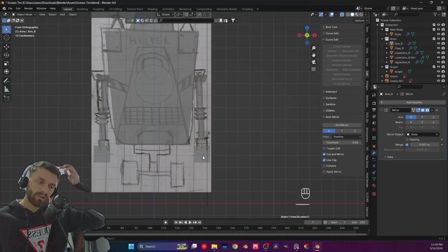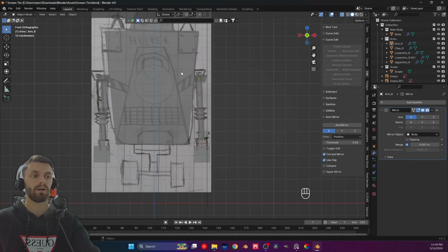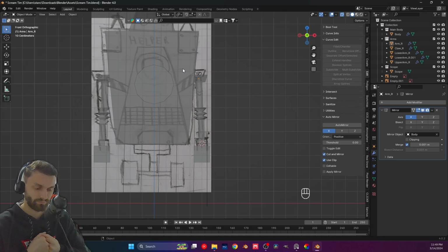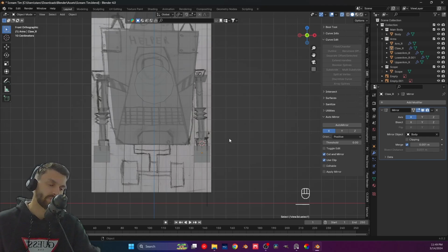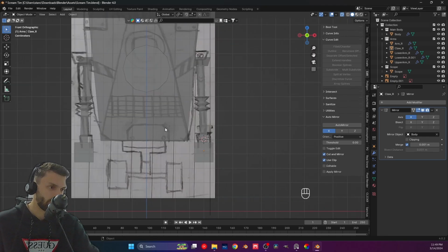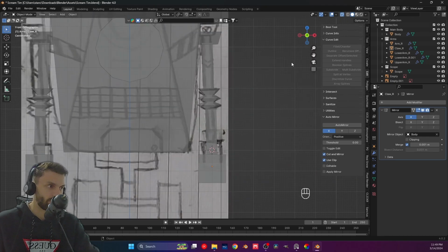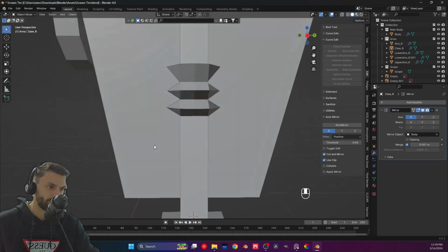And what that does is it will take the modifiers that this shoulder has, and it will apply them to the others as well. However, you have to understand that when you do this, you copy their modifiers. So if you have, for example, another modifier on the claw here, and you copy the modifiers from this one, the modifiers that you had previously on this will disappear and will be replaced by all the modifiers that you found on the object you took the modifiers from. All right, so just a little warning for you right there, just so that you don't get tricked by that.